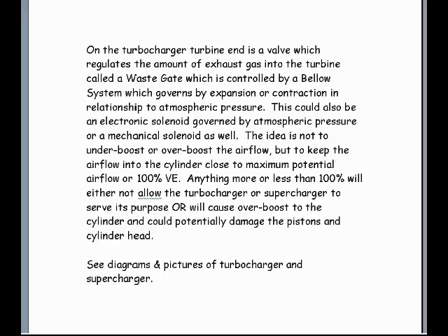called a wastegate, which is controlled by a bellows system which governs by expansion or contraction in relationship to atmospheric pressure. This could also be an electronic solenoid governed by atmospheric pressure or a mechanical solenoid as well. The idea is not to underboost or overboost airflow, but to keep the airflow in the cylinder close to the maximum potential airflow or 100% volumetric efficiency.